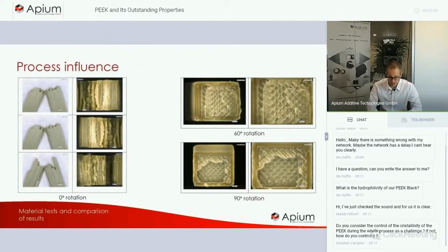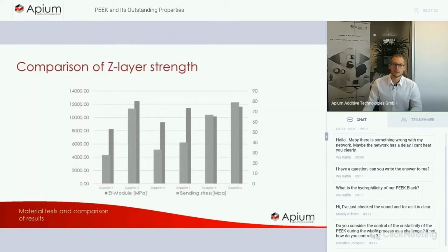And layer adhesion is something we are looking deeply into. So what we've done just recently was we have been comparing different suppliers for PEEK material and did internal testing, mainly on 3-point bending tests.